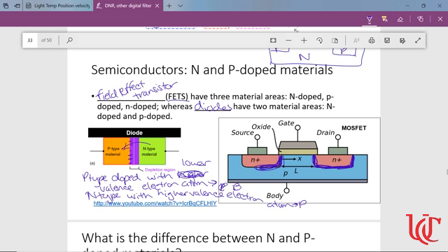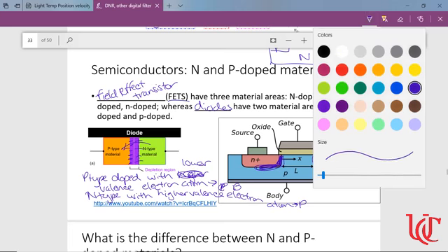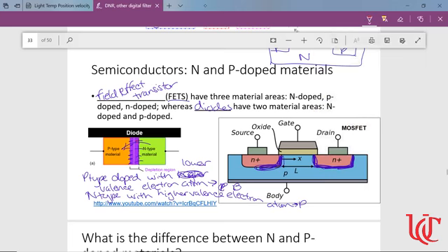Okay. And in the P-type, really, those were holes. They've now got filled with an electron. What happens at the depletion region then, where these electrons move from, on my N-type material? What charge am I left with there? Positive charge, because I lost an electron from that. So all of these, make them red so we can see that maybe. All of these in the depletion region ended up positive, because the electron moved from my N-type material, but right where it's close to it, over to here. And if I lose that electron, I've now lost a negative charge, or made it more positively charged.